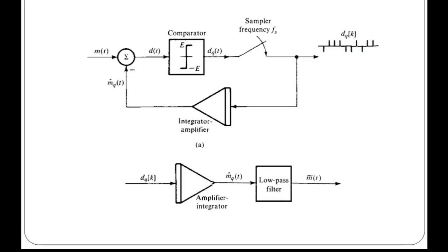So by knowing only plus or minus, by comparing this, whether the signal level is positive or negative, we will denote this by 1 or 0. When the step is reduced, 0 is transmitted, and if the step is increased, 1 is transmitted. Hence for each sample only one binary bit is transmitted.